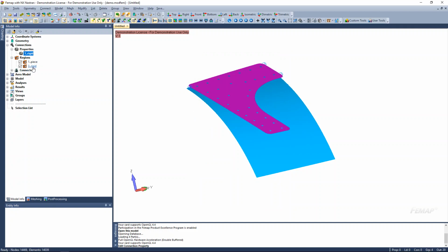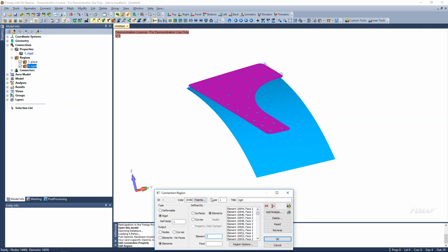If we look at the actual surface definition itself, recall that I said that all of the nodes of a rigid surface get tied back to a single reference node. In this case, that's the reference node, node number 1. So all of my constraints for the rigid surface go on node number 1. One thing to note that I don't think is described in the documentation is that node number 1 has to be a node by itself. It cannot be part of the rigid surface. It has to be basically a standalone node. If I was doing a forming operation like stretch forming, and I actually wanted to move the tool, then I would define that movement or that force on the reference node instead.